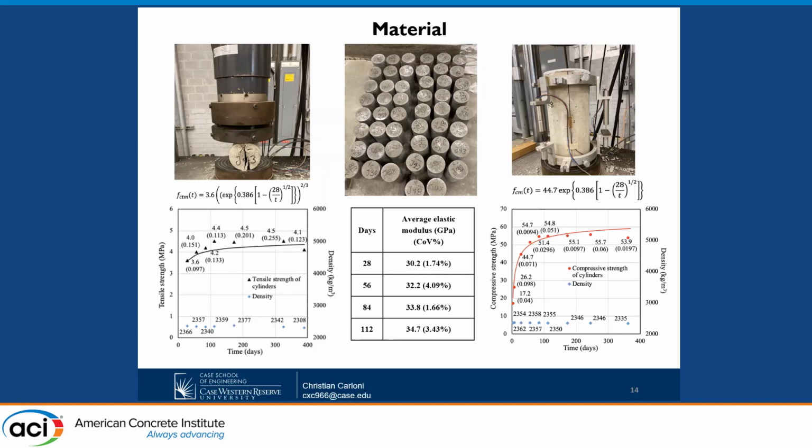The reason being that this test, especially the large ones, requires a day or 2 just to set up each test. So if you put together all the tests that we did, we didn't want to spend 2 months testing while the concrete was still young enough that there would be a difference in the strength. So as you can see, we waited. This is the tensile strength and the compressive strength over time. We waited until there was a plateau in the strength, so that we were sure that the concrete was, at that point, still maturing, but at a very, very low pace.